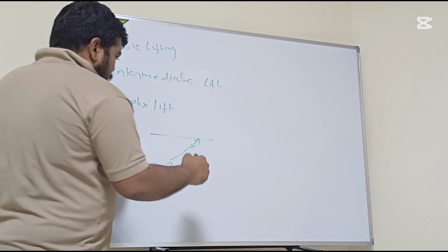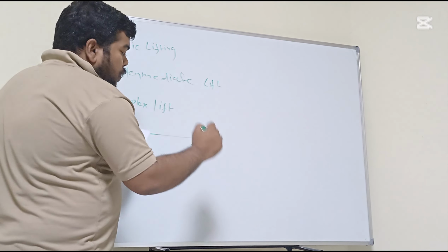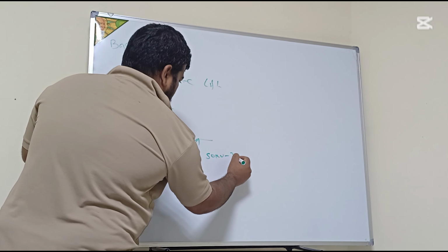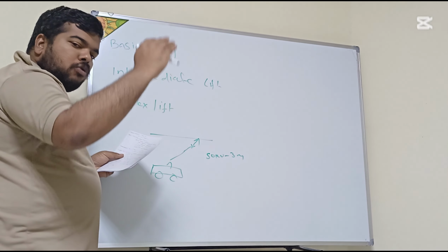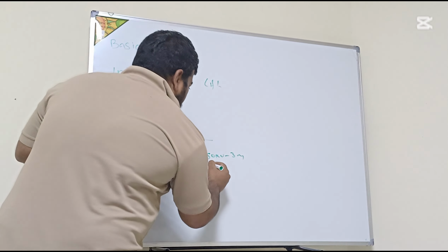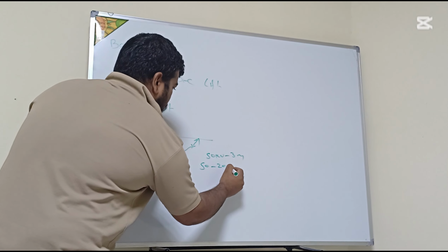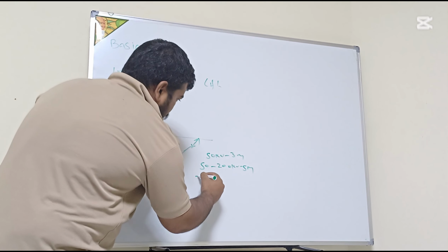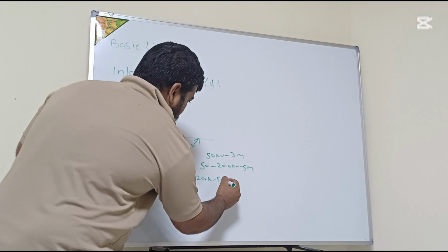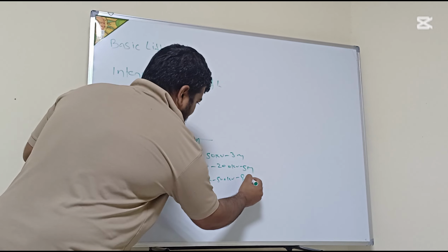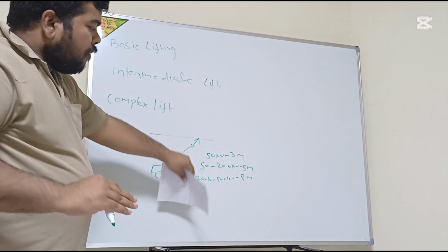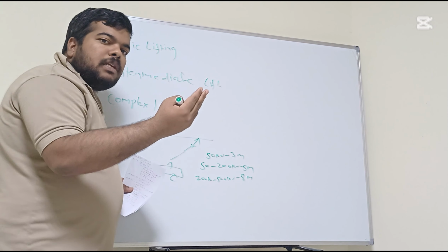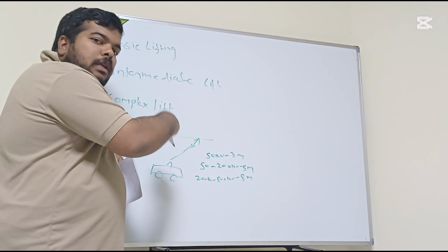As per BS 7121 standard, for up to 50 kilovolt you have to maintain 3 meter. From 50 kilovolt to 200 kilovolt you have to maintain 5 meter distance, and from 200 kilovolt to 500 kilovolt you have to maintain 8 meter distance. So what about after that? There is a short formula by which you can identify the minimum distance required when you are working nearby any live lines.